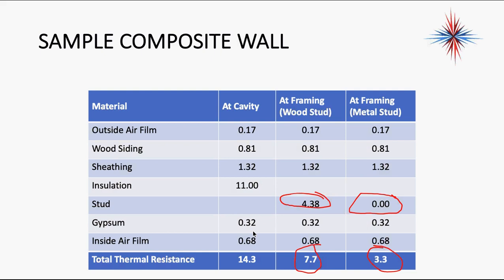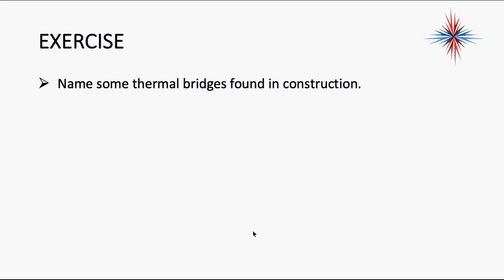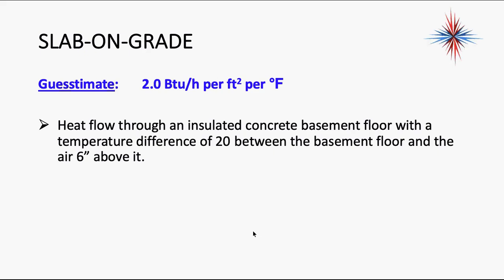Depending on the temperature difference between the indoor and the outdoor, there's no insulation for a plain wood stud. And I do have to go find those insulated studs. I have to go look at those as soon as I can get into a store. So, a thermal bridge is any substance that allows a direct connection between an inside wall and an outside wall and allows heat to flow through it.